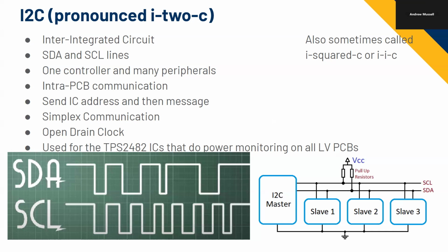This also gets a little bit into how digital memory is stored. You have a clock signal because, like I said before, we have a flip-flop, which is a way to store memory. You need a setup time: the data needs to be good for some amount of time before you latch the memory. Then you need a hold time, so the data needs to be good for some amount of time after the clock edge. To respect those times, that's what you have the clock for.